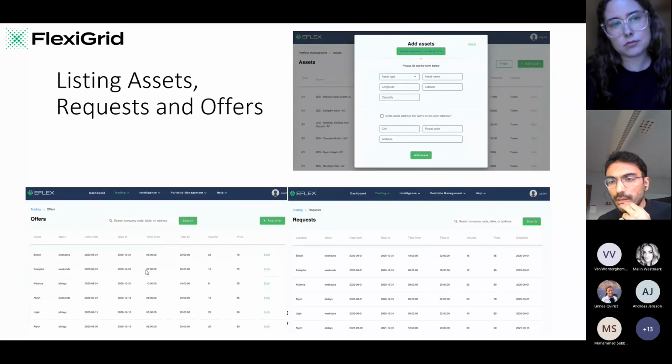I can mention something here regarding the capacity limitation product: one of the benefits with that is that you do not need this sub-metering. You just need to read the net load from the smart meter, and whatever is happening behind the meter is the flexibility provider's decision. They can provide flexibility with whatever technology they want. They just have to keep their net load below some cap, and we can validate it by reading the net load from the smart meter.